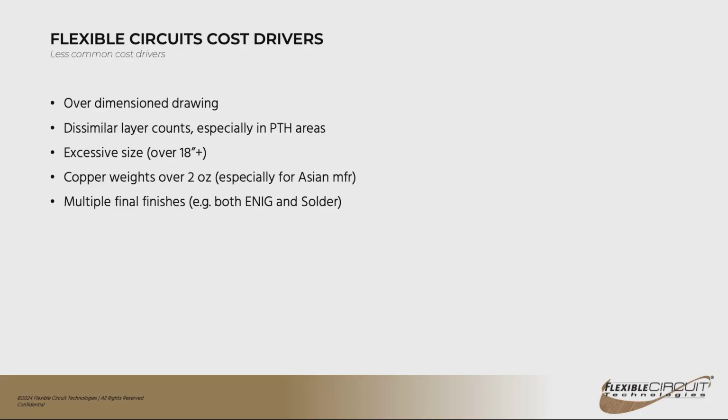We don't see silver used as much for shielding, but when it is, it's very common to have that silver go through the cover and make contact to copper pads or copper conductors below it. So you have continuity through the silver shield. So that is something that's very common and can be done very easily.